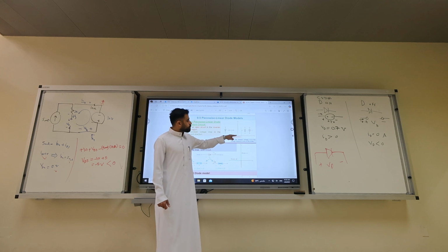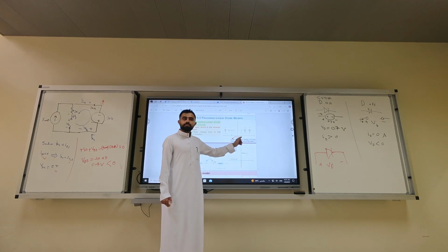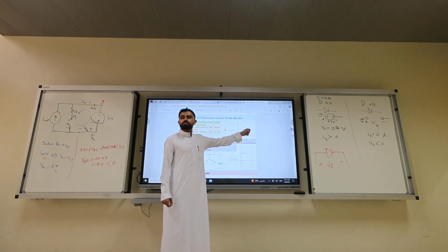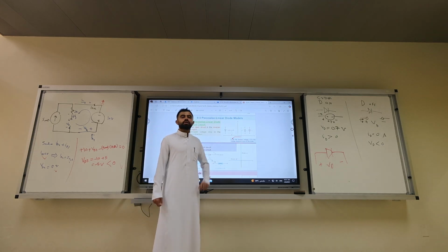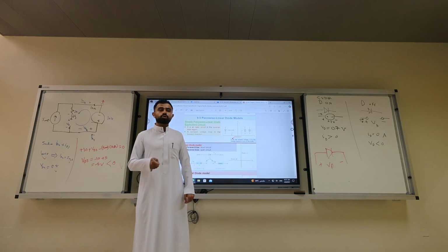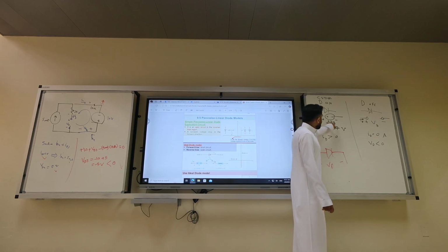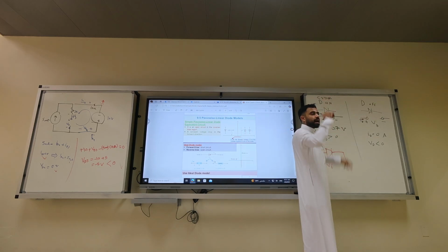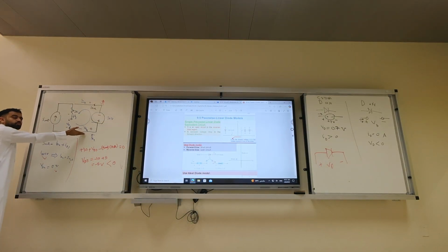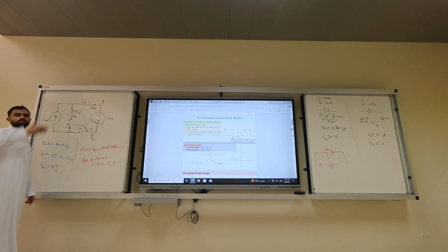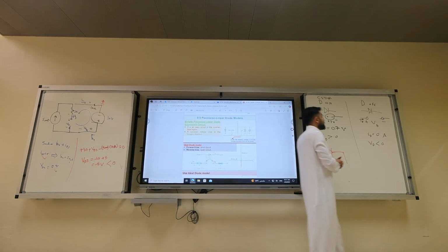Do you remember the curve where we had it like that? The curve is now shifted to VF, where VF is 0.7 volts. VF is the forward voltage, the voltage required to turn on the diode. This implies that in order to ignite the diode and let the current flow, you have to apply a voltage more than 0.7. That will happen even if you connect it with 10 volts, since 10 is way larger than 0.7, so it should turn on. The same guessing technique we used before, we can use for the diode.